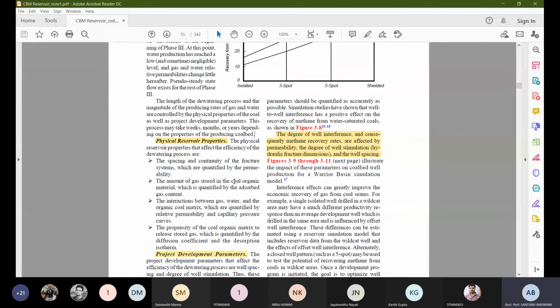Now let me tell you, you have studied rock mechanics. You know that coal can also be taken as an elastic body, and for each elastic body there is a stress-strain graph, an elastic limit, a fracture, a peak stress, and a failure. For each material there is an elastic limit. That means if you apply pressure, it deforms and contracts, and if you remove the pressure, it returns to its original state. That is within the elastic limit.